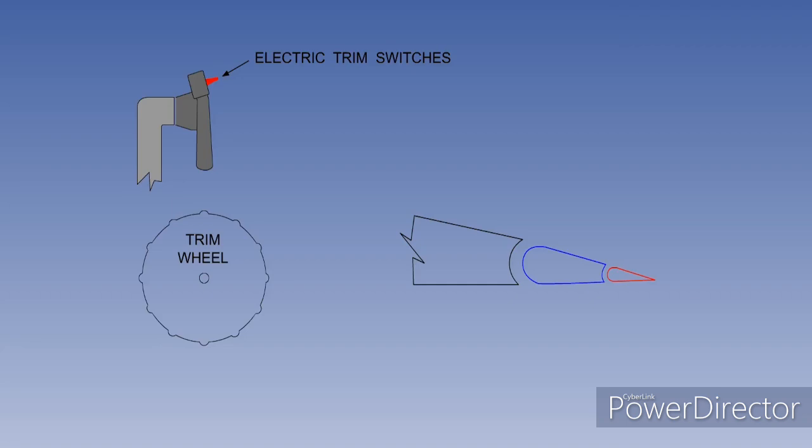The majority of smaller aircraft have an exposed trim wheel in the cockpit, which the pilot can use to move the trim tab. The trim wheel works in a logical way. Move it down by its rear edge to trim the aircraft nose up, as you will see shortly. Some small aircraft and all modern jet transport aircraft have trim switches mounted on the control wheel. The trim switches also work in a logical way. Move them down to trim the aircraft nose up, again, as you will see shortly. All control movements in the following animations are exaggerated for clarity.